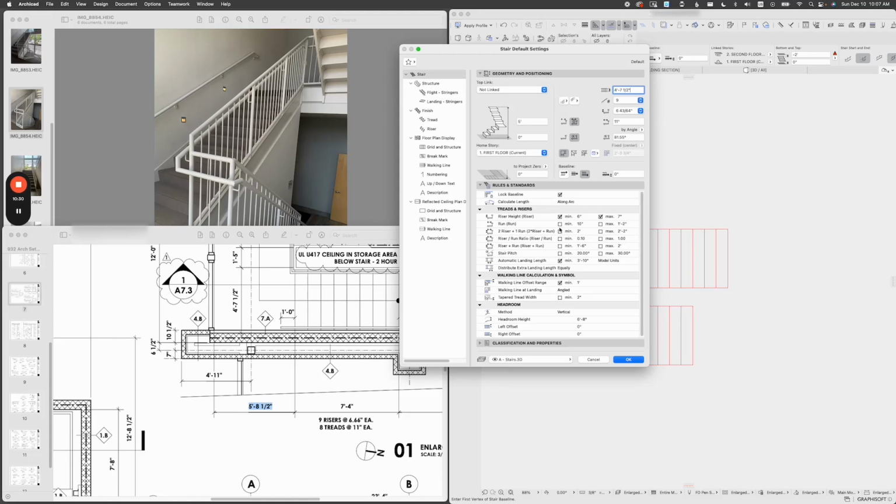That should be it. We should be ready to go to model the stairs. I think the only setting that is really important is also this turning type option. Sometimes by default it says minimum riser offset, and it says 0, 0 here. You can also change it to fixed riser offset, but I think in our situation it will probably not matter. We can leave it as is.